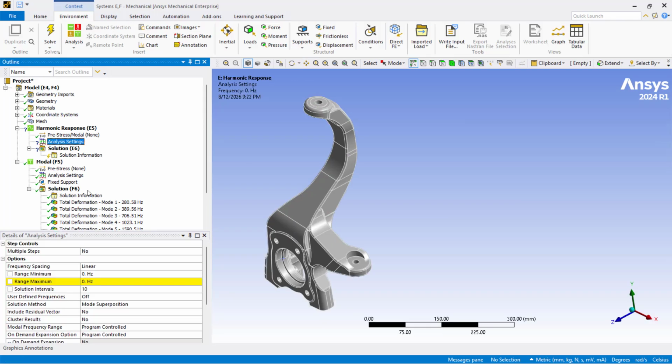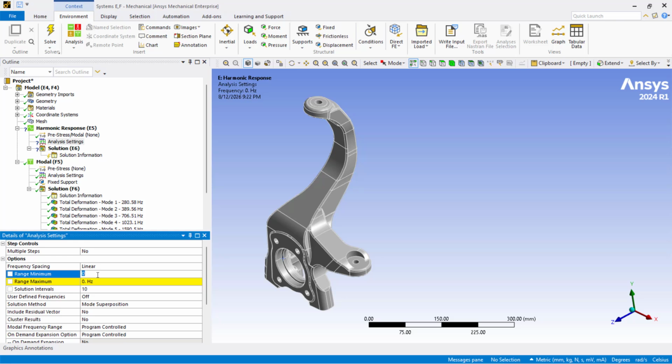One check. Previous model, what actually the natural frequency we got? Can we check that one? Since we had added the material, that frequency should increase. Previous one should be lesser than this, correct? What is the relation between the stiffness and mass versus frequency?